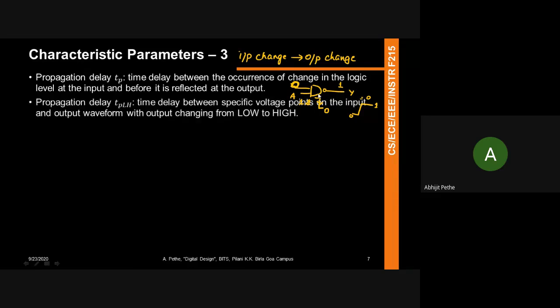And in the most generic case, this is something you'll understand when you start learning about transistors: we talk about two kinds of transistors, NMOS transistors and PMOS transistors. One is a transistor that works with electron current, one is a transistor which works with hole current. Some of you know electrons move faster than holes. And so the NMOS transistor tends to be faster than a PMOS transistor. Or an NMOS transistor can conduct more current for a given voltage than a PMOS transistor.